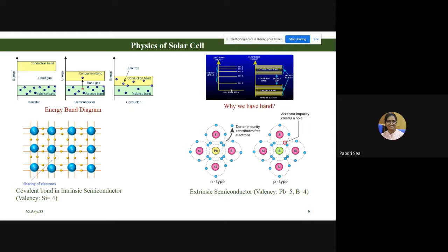Now conduction band is where the empty states of p level will combine together and will give you conduction band. So conduction band means empty states, available states for electrons where you can have electrons but there is no electron. So possibility of having electrons is there in conduction band, but in valence band you have all the electrons. In conduction band there are no electrons at absolute zero temperature. Why am I saying absolute zero temperature? Because temperature plays a major influence on the movement of electrons. Temperature provides energy, thermal energy of fluctuation.